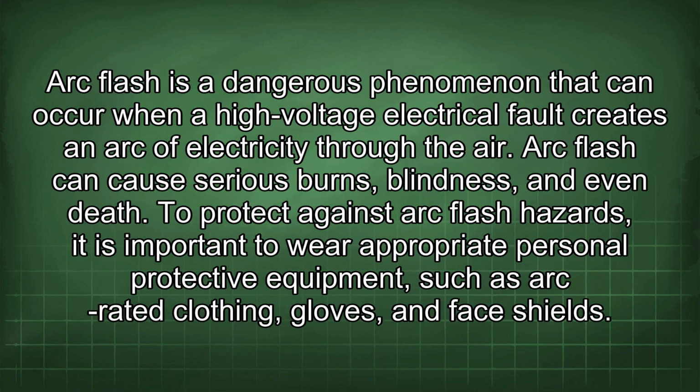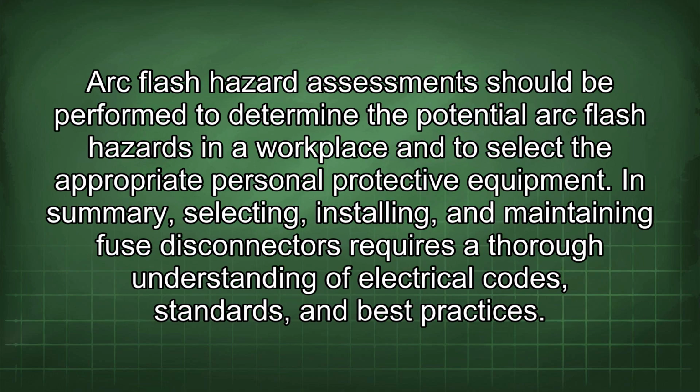Arc flash is a dangerous phenomenon that can occur when a high-voltage electrical fault creates an arc of electricity through the air. Arc flash can cause serious burns, blindness, and even death. To protect against arc flash hazards, it is important to wear appropriate personal protective equipment, such as arc-rated clothing, gloves, and face shields. Arc flash hazard assessment should be performed to determine the potential arc flash hazards in a workplace and to select the appropriate personal protective equipment.